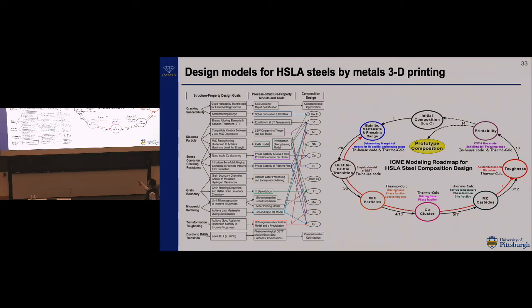So basically you want to have a certain property of the microstructure or certain phases, then this model can provide information here, okay? And then if you say, oh, the bainite martensite temperature, I want to control to less than 200 degrees C, then if a composition is higher, you exclude it, okay? Then you run the screening, and then you get the prototype design. So that's the thing, all right? You have to understand the very fundamental models, not only in CALPHAD, but CALPHAD can provide essential information to support your prediction and design of the material.